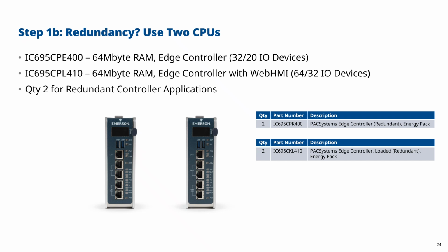Combine that with the built-in PROFINET controller using LAN 2 ports, which includes MRP capability, and now you've got a hot standby controller system with a fault-tolerant I/O network. So very simple to build up redundancy using 2 CPUs rather than 1. Effectively, you're getting redundancy for the cost of a spare module.